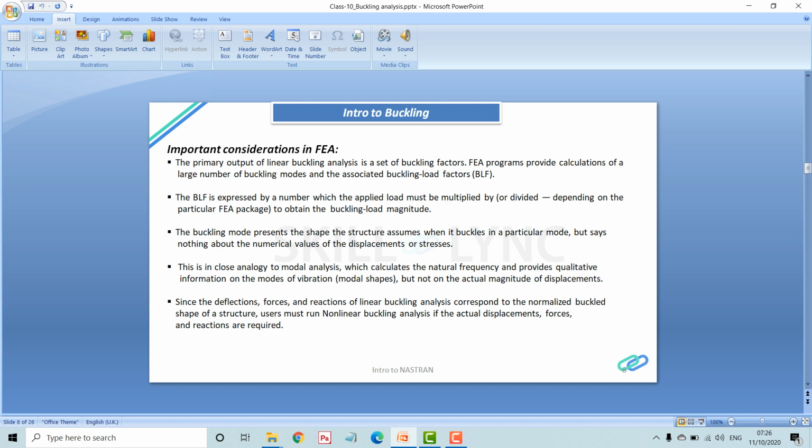Suppose you're running a nonlinear analysis, and with respect to time, at time step t equal to 0, you applied some loading to the structure, and there might be different support reactions coming from the structure. Once it underwent buckling, at time t equal to 10 seconds or 15 seconds, there might be a variation in the support reaction, because whenever the structure undergoes buckling, as the configuration changes or when it gets deformed, the distribution of the load within the structure obviously changes. So there might be a variation in the support reaction. That's what this last point meant.